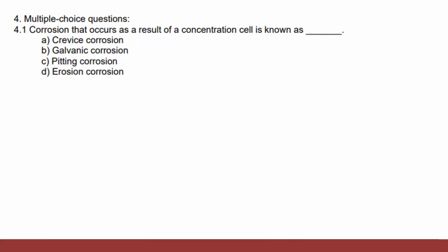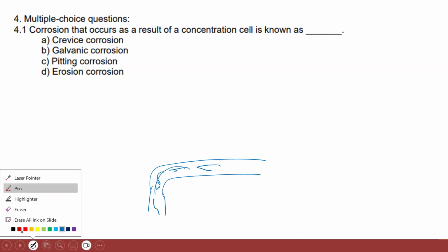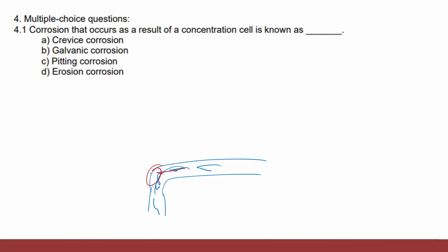It's with the force. For example, you have metal pipes, and fluids, water or any other fluid, are flowing here. On these points, forces are applied and the corrosion is happening much faster because of that force. So the elbows, any weak points, any junctions, will corrode faster because of the force. It is force and the chemical reaction both happening together.